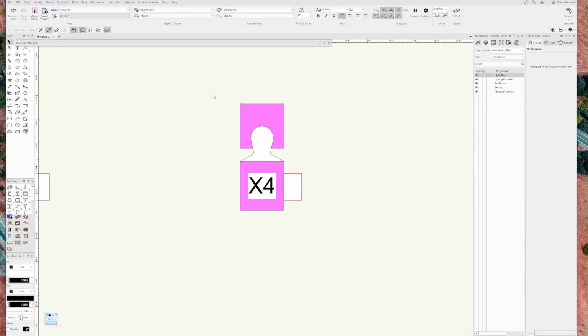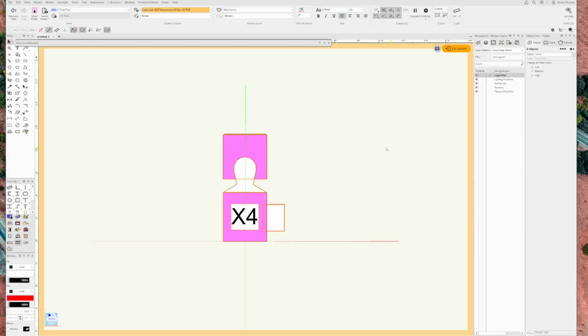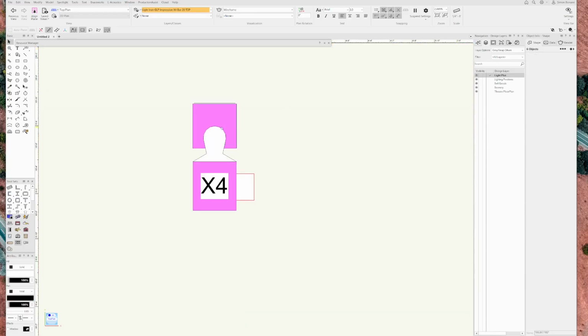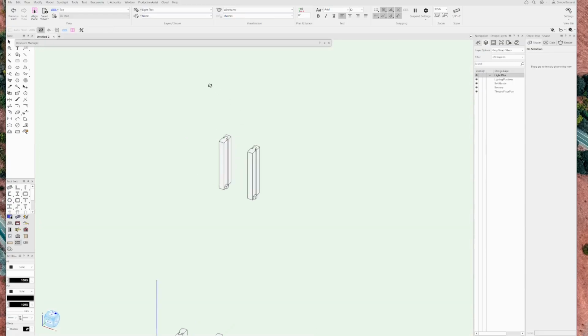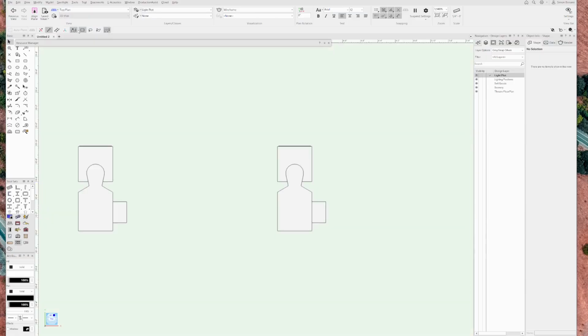And if you're curious, here's what could go wrong if we make a mistake or not sure what we're doing in between a 2D and a 3D components of a hybrid symbol. Let's say I re-edit the 2D component and voluntarily put it like this, which is not necessarily obvious, but that could lead to quite important issues. When you look at it from here and you just quickly flip and look, everything looks fine. But if you go straight from top plan to top, there's quite a difference between your top plan and your actual 3D install that could cause some issues.